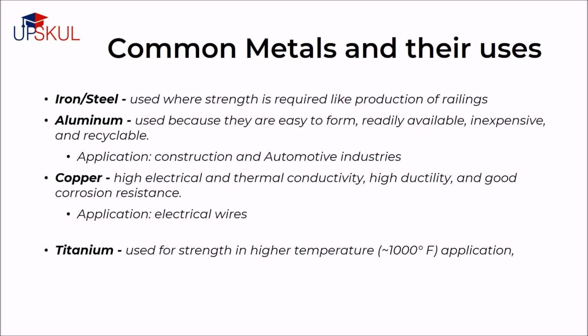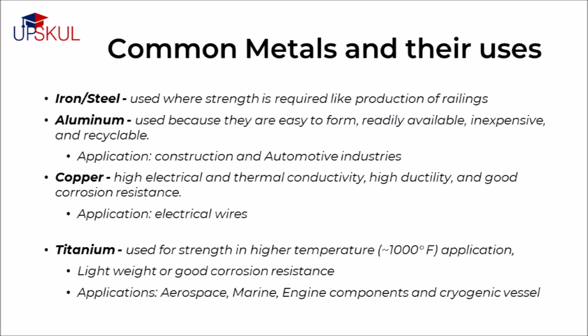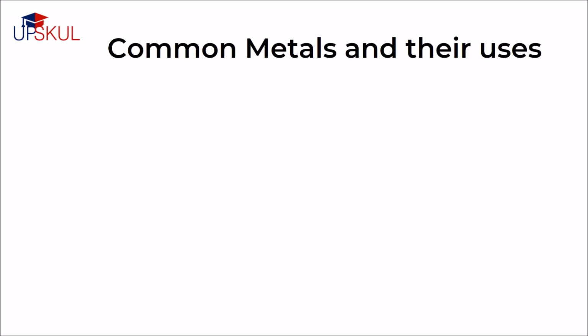Titanium alloys are used for strength in higher temperature applications. It could be a temperature around 1000 degrees Fahrenheit when component weight is a concern or when good corrosion resistance is required. They find application in aerospace, marine, engine components, and cryogenic vessels.